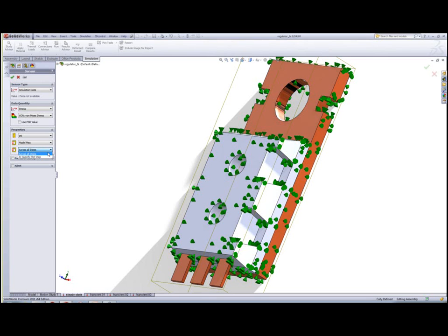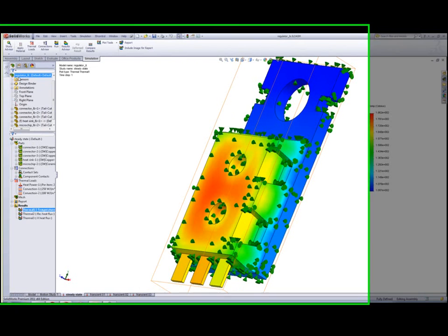And the one that's not shown here is only for frequency studies and buckling studies. It's another option that says a specific mode shape, which for obvious reasons is only for frequency or buckling style studies. This option will only show that particular mode shape and look at that sensor. Real good stuff. So now we can go in and we can take sensors for these transient studies.